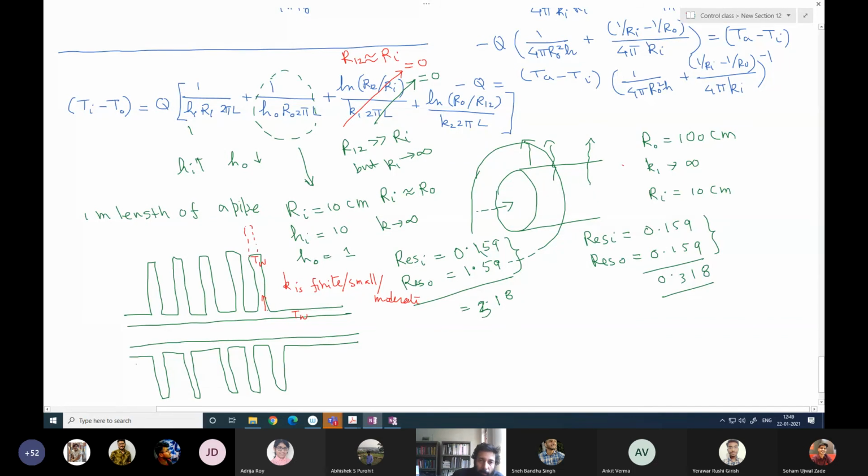So temperature from T wall will gradually change, and after a certain distance, a certain length of the fin, it will reach something very close to T ambient. So there will be very little or no heat transfer from the fin to the ambient for those cases. So a fin is efficient only up to a certain length. So we have to analyze a fin for its efficiency.